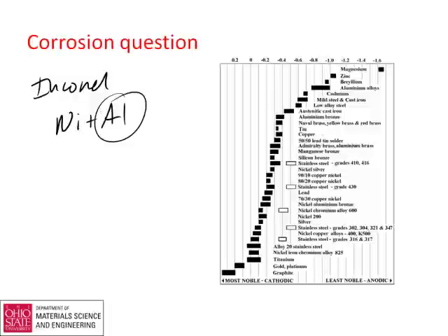And the answer that is correct, and this comes from Jerry Frankel, and I just used the questions he used with that lecture, and wasn't thrilled with that question, is he said really nothing should happen. Inconel doesn't show up on here, but you see these nickel alloys sit very close to one another on this galvanic series, which means that they should be fairly compatible.